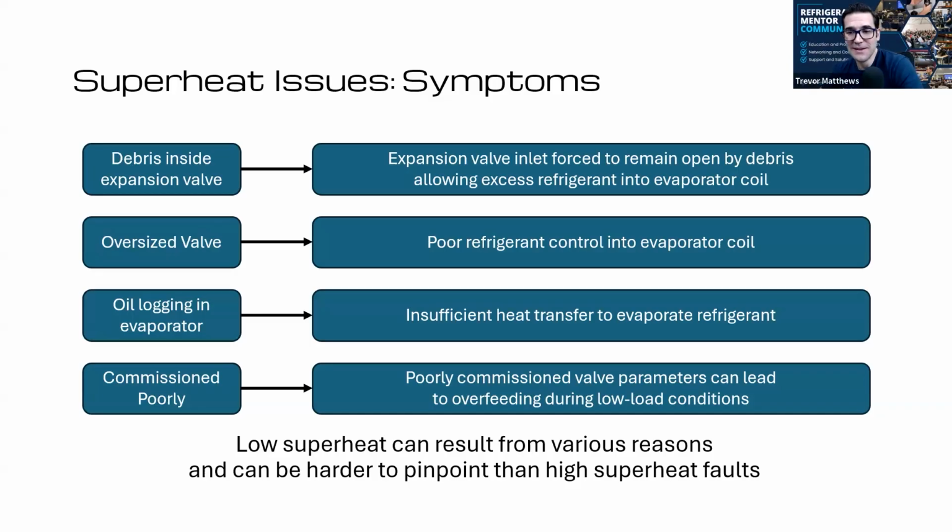What are your thoughts? Yeah, no, it's a great feature. And like you say, you can spot a step change when the valve's starting to become blocked, and it starts increasing the percentage opening. Or say your suction probe falls off, it's still getting the temperature from the case, or it becomes slightly detached. Then you'll start to see the valve go 0, 100%, 0, 100%, where it's not seeing the superheat it wants to calculate. So yeah, it's good for diagnosis and pinning things down without a doubt.